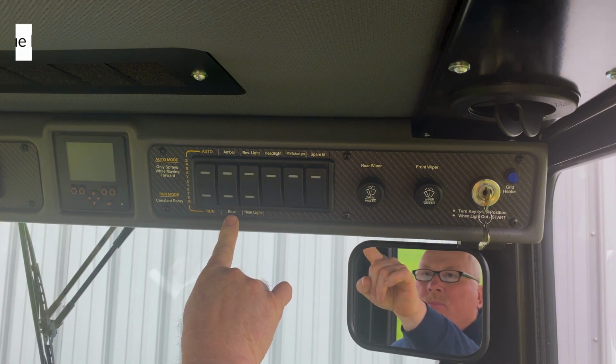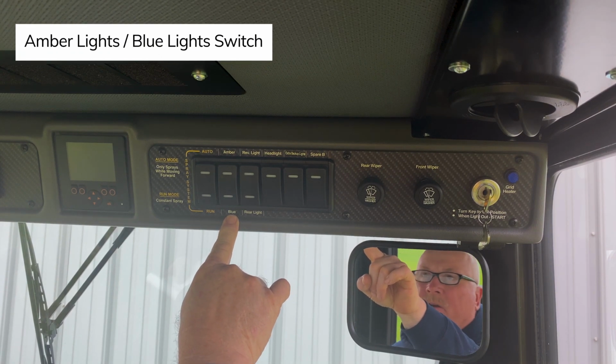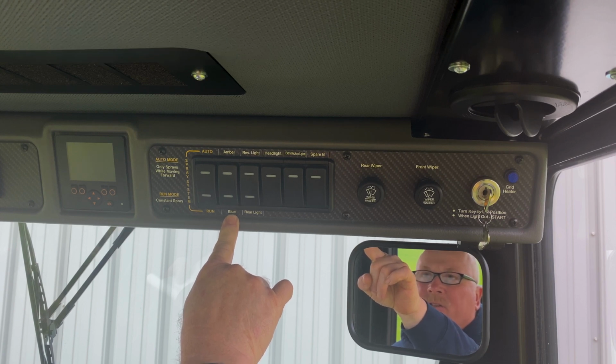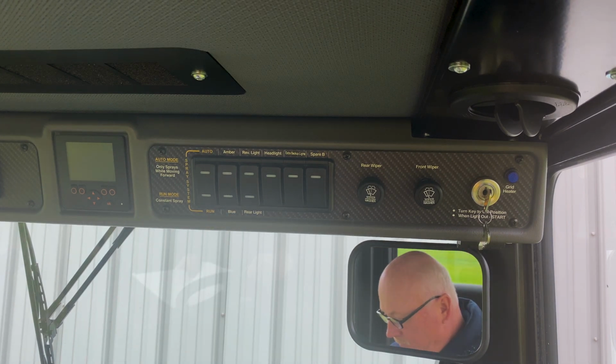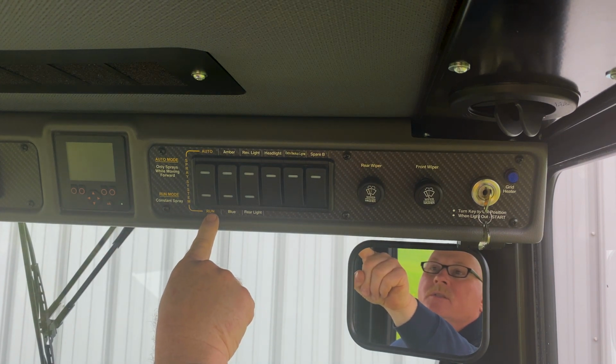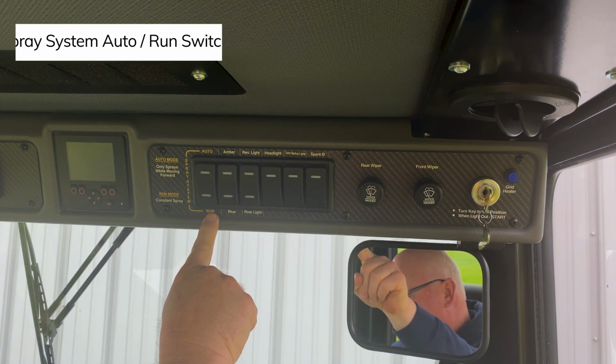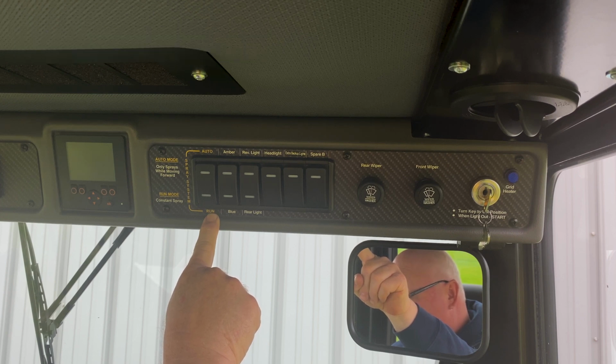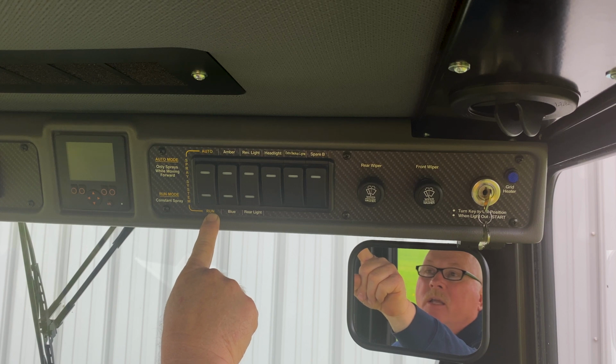This is the amber blue switch. This will be for your external flasher lights, whether you select amber or blue flashers. Spray system, auto run. This switch controls 12 volt power to the electric pump for the rear mounted water tank. In the auto position, it will spray only when the tractor is moving forward. In the run mode position, it will provide constant spray 100% of the time.